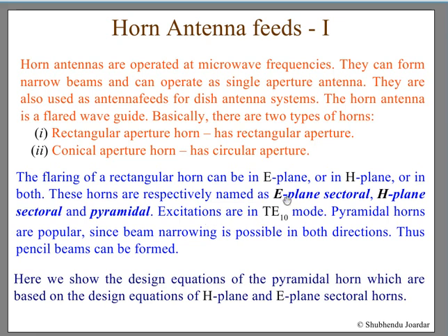So here we use the TE10 mode, that is the simplest one, and most of the designs use this one. So that makes a very efficient way of using a rectangular waveguide in TE10 mode.